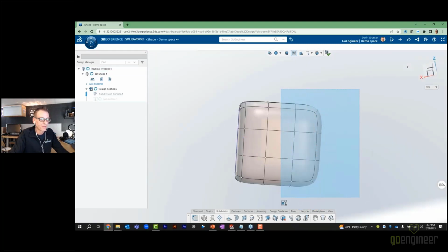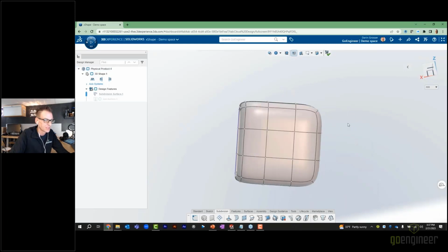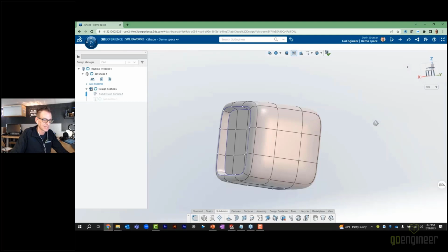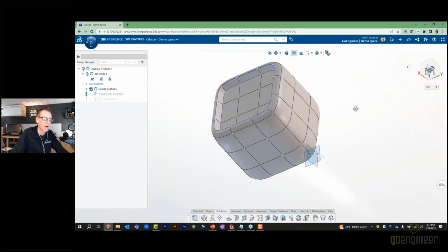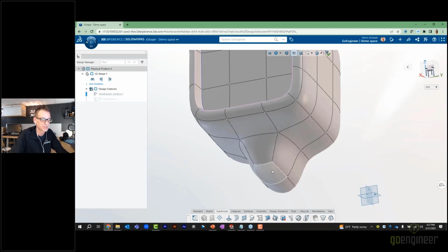Now, the last couple of things that I'm going to do with this, and what I would actually do had I made my electrical or housing panel on this, is I'm going to go ahead and just add a stand or a mount to the bottom of it. Now, by doing this, once again, I like to grab multiple faces and use the extrude tool, because that really is adding material to this. It just protrudes out, and if you continue to do that, it's going to add additional material to that.